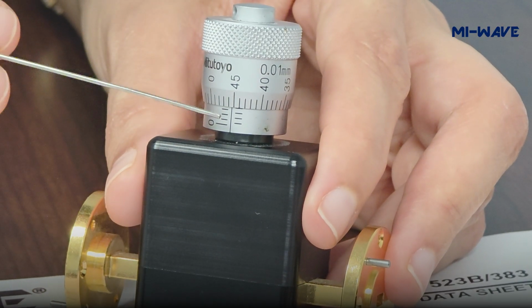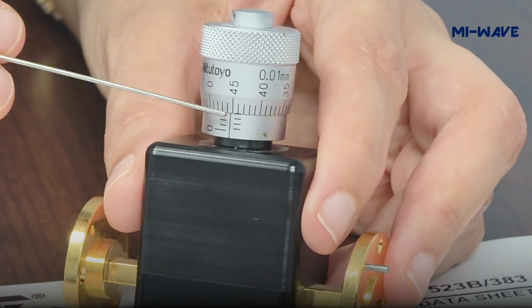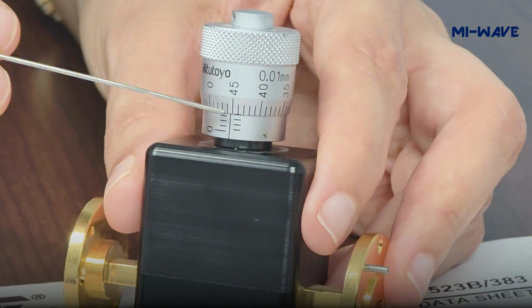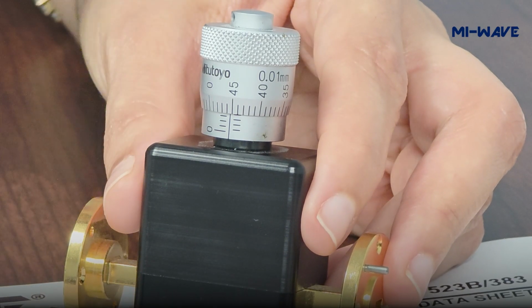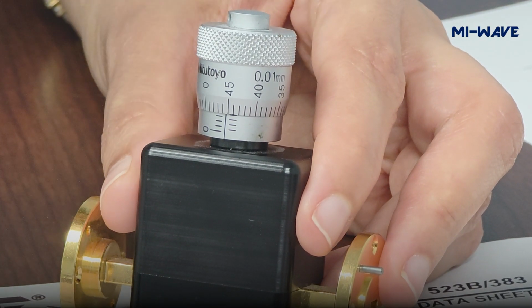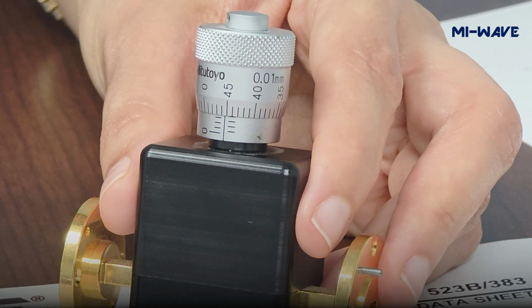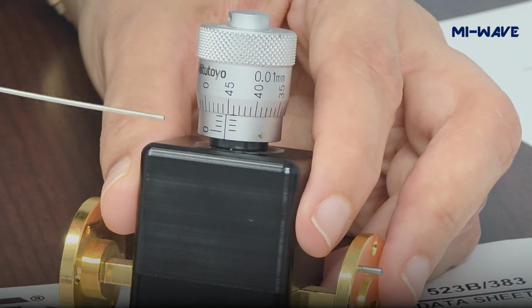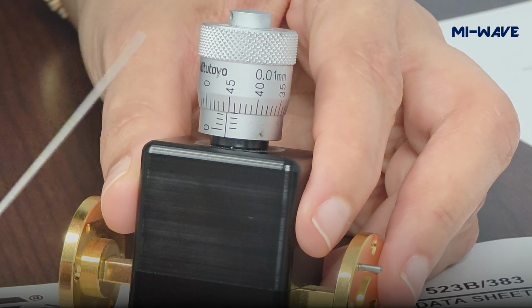Here on the vertical scale is the indicator. So when you are changing the attenuation, make sure that this indicator, the vertical scale, faces towards you. For this attenuator, to increase the attenuation, the dial knob will move counterclockwise, and to decrease the attenuation, you will have to rotate this micrometer in clockwise direction. On the vertical scale, each division is 50 points. So let's read it out.